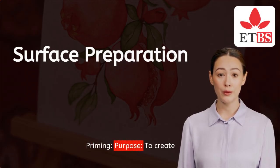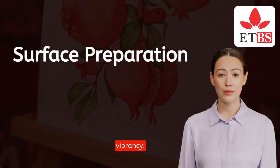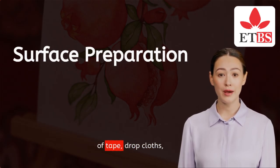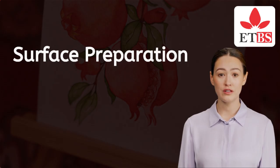Priming. Purpose: to create a uniform surface, enhance adhesion, and improve colour vibrancy. Types of primers for drywall, wood, plaster, and metal surfaces. Masking and protection. Use of tape, drop cloths, and plastic sheets to protect floors, furniture, and fixtures.